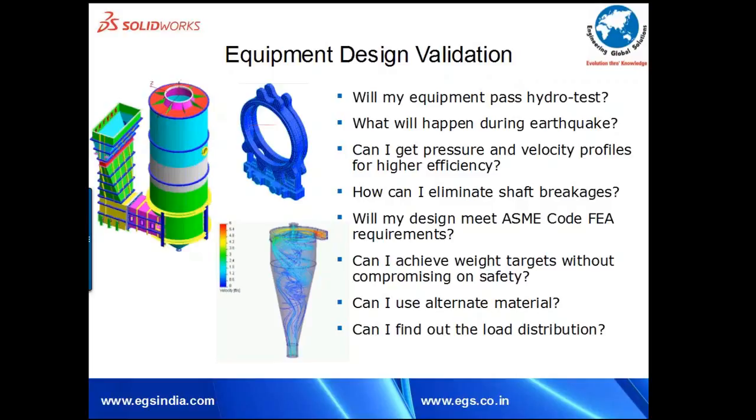A lot of times, if you have chosen a flange thickness, a nozzle design, or a pressure vessel thickness, either for vacuum or for internal pressure, for a pulsating load for example, you are going to be deciding for certain cyclical stresses that are coming as a result of the operating load, which you are trying to address by eliminating it as a failure mode during your warranty calculations.